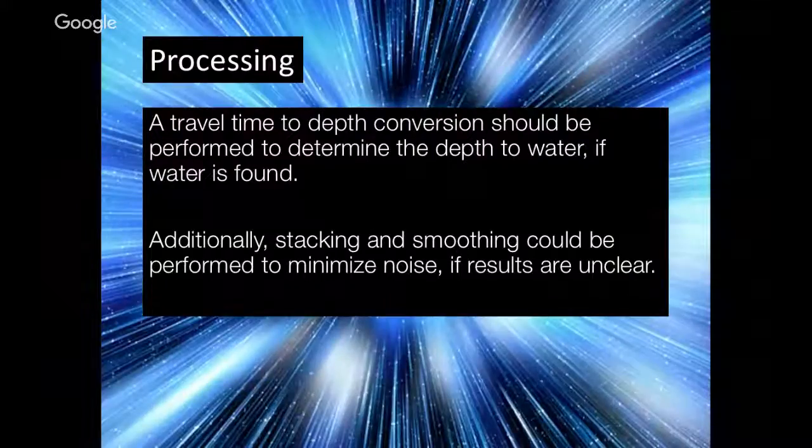For our processing, we just need the travel time to be converted to depth so we can find out to what depth the water is at. And for additionally smoothing up the data, we can use stacking and smoothing to get better results if there's noise.